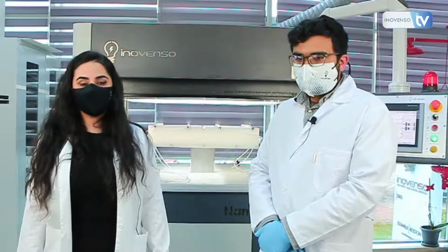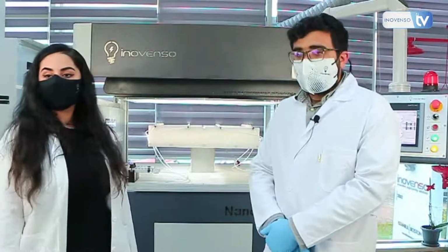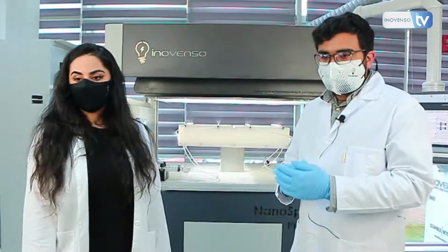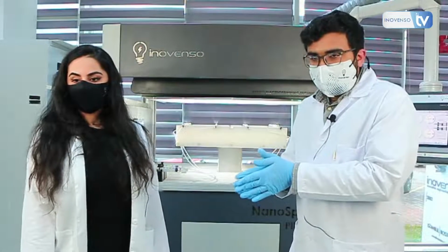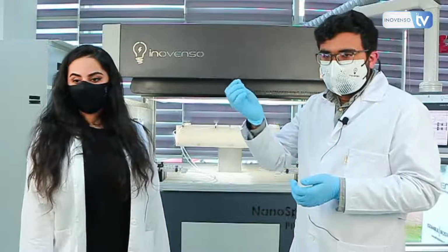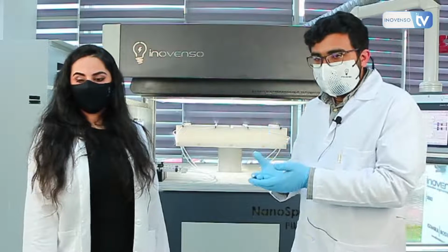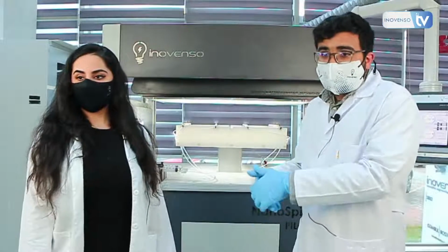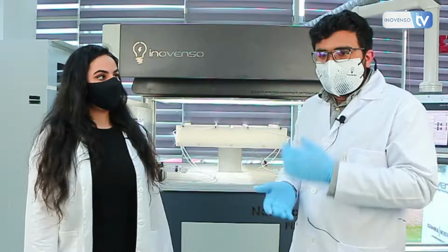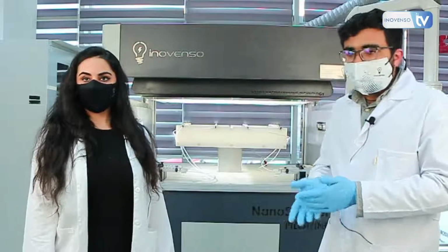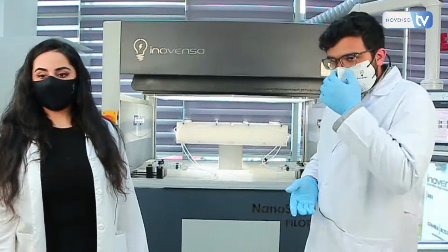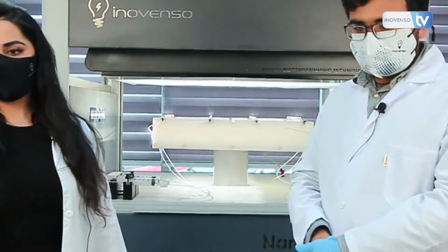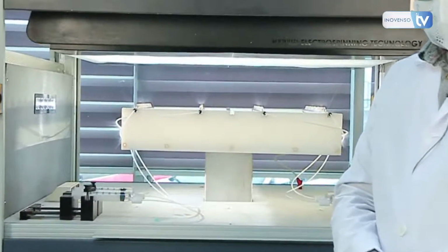Another question: how is the cleaning process of the needle? Good question. It's easy to clean the needles, or excuse me, the nozzles rather. You have to clean it with the solvent that you're using. In cases of clogging, you just need to use a pin or small needle to open it out. For example, if you're using a polymer like PVDF and the solvent is DMF, then to clean it you would use DMF. But for a more generic approach, you can always turn to acetone and water, and then dry it. It's also easy since our hybrid nozzles are designed with large holes to prevent clogging.